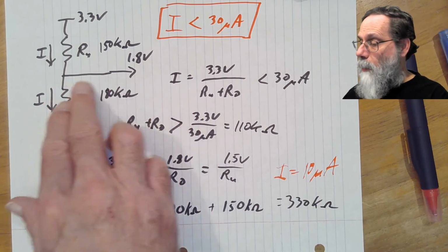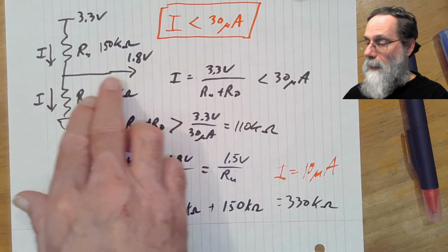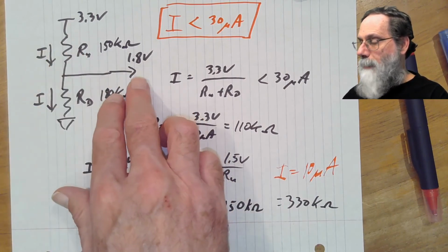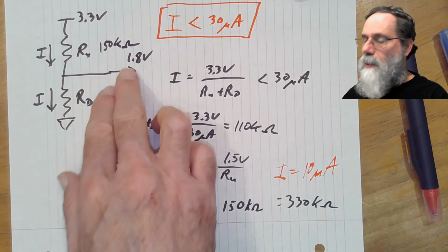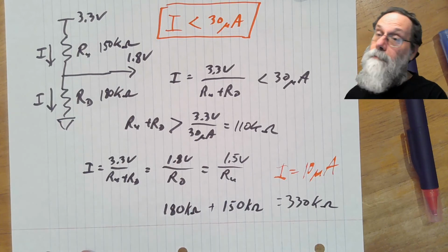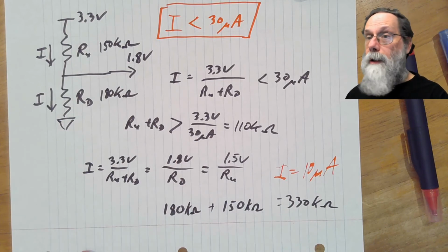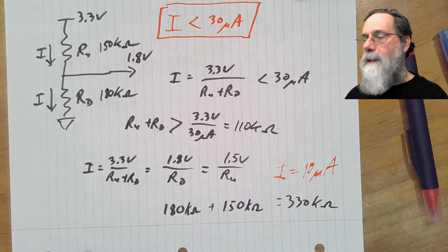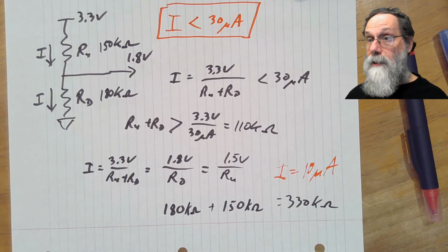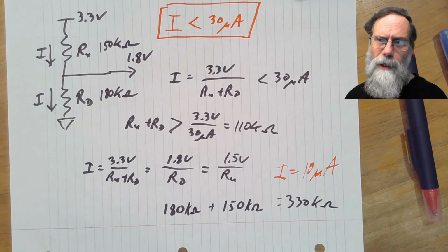Do I care about what the output impedance is here, how much resistance there is basically in series with this voltage? Maybe, maybe not. And so quite often you have to look at, okay, I've got a lot of different design solutions here. The first one I come up with is not always the best one for the application, and you need to sometimes go and ask the person who originally asked you to design, well, I've got a couple different designs here.